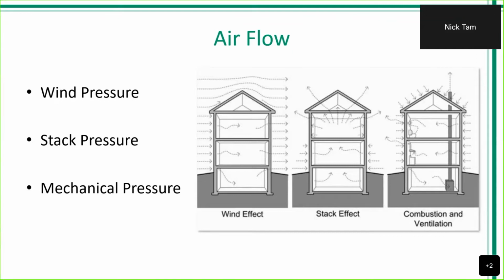When we talk about fan pressure, this is going to occur from mechanical systems that draw air throughout the building, creating both positive and negative pressures within the structure. Because of this, we will get both infiltration and exfiltration. This is where we'll see things like a plenum chamber, which is essentially a type of ventilation or air transfer system that will facilitate airflow throughout the structure.